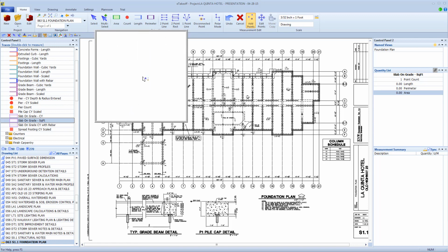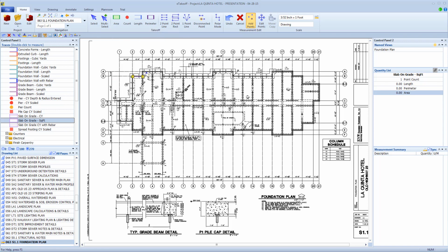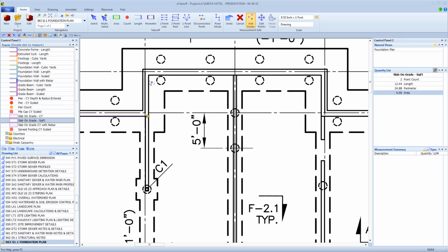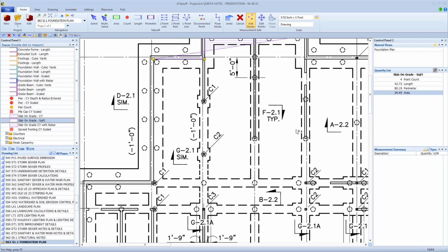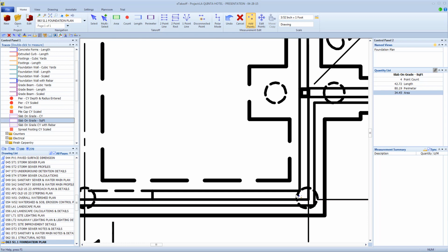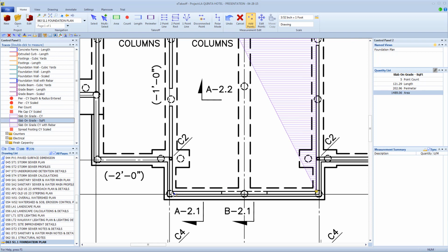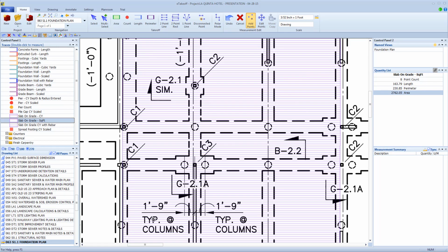Second, you can zoom into the point where you want to start your measurement by pointing your mouse pointer and rolling the scroll wheel forward to zoom in and backward to zoom out. You can move or pan the drawing around by pressing and holding down both left and right mouse buttons and dragging. You can use the zoom and scroll tools while measuring. To finish your measurement, you can push the Enter key or the letter S key on your keyboard.